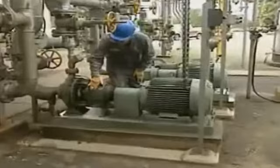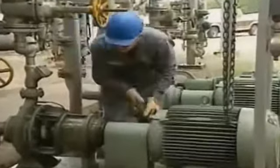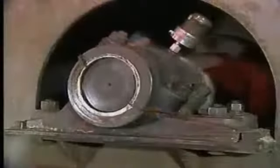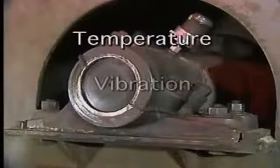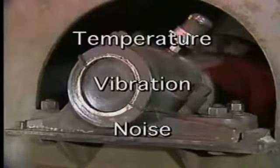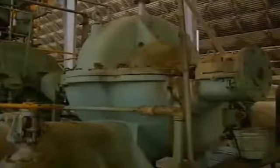Since your job involves maintaining equipment that uses bearings, it's important for you to be able to tell if a bearing is performing properly. There are three major indicators of bearing performance: temperature, vibration, and noise. Any of these three indicators can provide evidence of whether a bearing is functioning properly. We'll look at temperature first. A bearing doesn't reach its normal operating temperature until after the equipment has been operating for a while. The amount of time that's required varies with each piece of equipment.